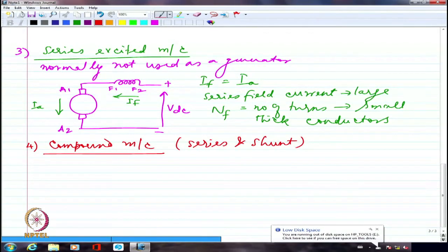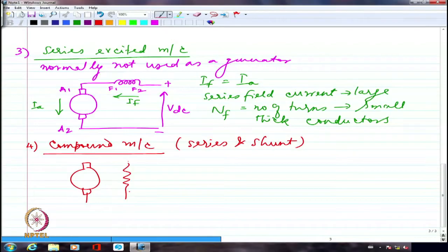So the torque developed is going to depend upon the demand from the load side in the case of a motor. If the mechanical load demand increases, I'm going to have more and more current. If I have a generator, depending upon what kind of resistance or load I have connected, I'm going to have more or less demand of current from the machine. So please understand this again and again. If I am talking about an armature, and I connect a small resistance, I am going to demand more current for a given voltage. If I connect a smaller resistance, I am demanding more current.